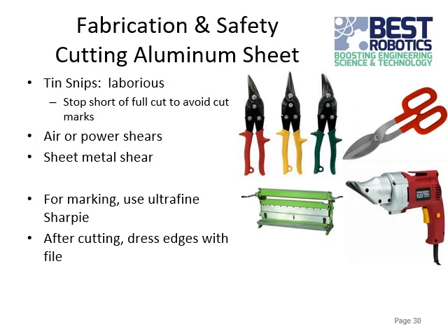For the aluminum sheet, because that's going to be a really wide and thin sort of thing, you're probably not going to want to use those tools I just talked about for the bar and the rod. For this, if you have tin snips, you can use those. It can take a little bit of time to work your way through it, but it should work. It might bend or deform the edges a little bit as you cut, but you can make it work.